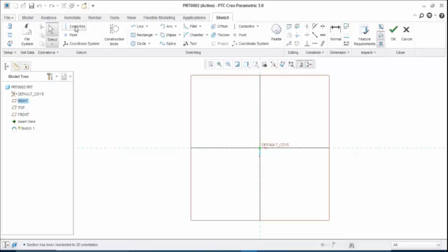Now, first of all, you cannot make any kind of mirror option or something like that with the reference of this line. Like relations, you can't put relations to those reference lines at all. Exactly. All the relations will be created with the help of this. If you are creating one circle here, it will take relationship automatically. So reference lines are very necessary. If reference lines are not available here, you cannot make anything. It will not let you go out.